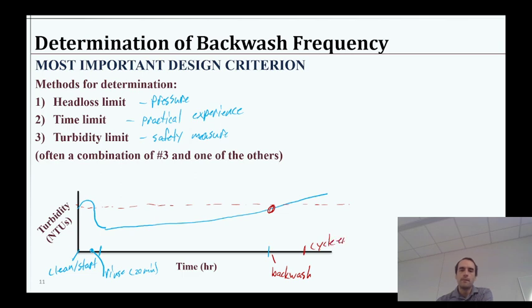And anything after we start backwashing, we're not actually monitoring the turbidity, right? Because at that point, we're no longer flowing forwards through the system, and so the turbidity monitoring is non-existent, right? So as soon as we hit that threshold, we would stop there. So that would be what it looks like for turbidity monitoring, and that's also why we see right here why we're not going to operate and use the rinse water for actual produced water.